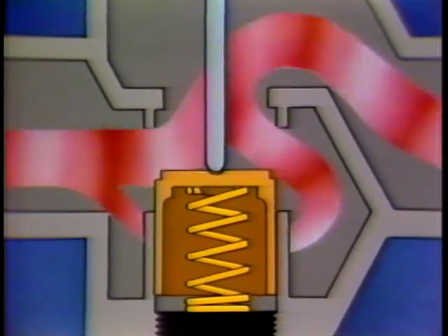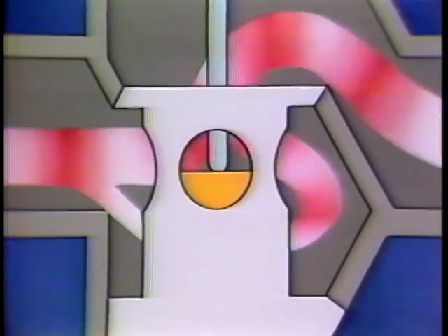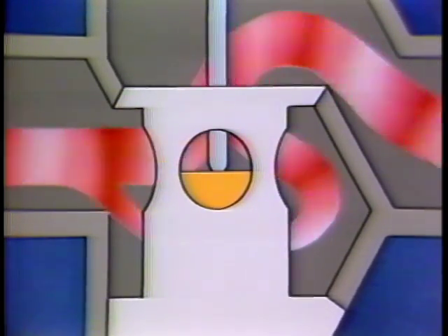The multiple circular ports also reduce noise and characterize the valve. If the port were square or rectangular, each increment of movement of the valve plug would cause an equal change in flow. With circular ports, the port area opened at the beginning of the stroke is much less than later in the stroke. Flow changes less in the beginning of the stroke, so the valve is less sensitive to turbulence in the pressure signal and maintains its stability during low flow operation.